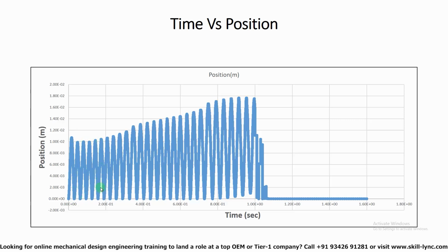Now the reason why the amplitude of this curve or amplitude of this wave, right, increases over time is because of the increased inlet pressure, right? So as the pressure in the inlet line keeps on increasing, the maximum displacement of the spindle is going to increase. And at some point, what we have done in our inlet pressure profile is that we have ramped the pressure down to baseline pressure, right? So the pressure is reduced, and that is why after some time there is this sudden drop in displacement and the valve shuts closed again.